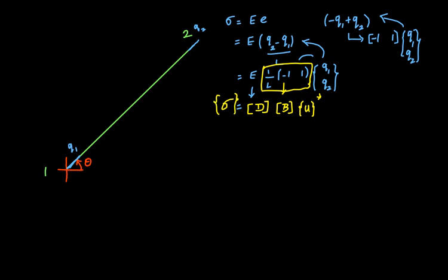In general, it's a column matrix. All right. Now, in the next step, I'm going to take from this term: stress is equal to capital D, which is Young's modulus, into 1 by L, minus 1, 1. And the Q matrix can be written as del matrix into U matrix.